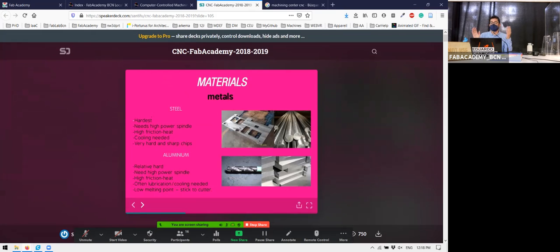Feed rate is the speed. Okay, this is about terminology. Horizontal speed is also called feed rate. In general, in CNC, horizontal speed is also feed rate. It's the amount of material that you're eating. I don't know why, but they usually have eating terminology.